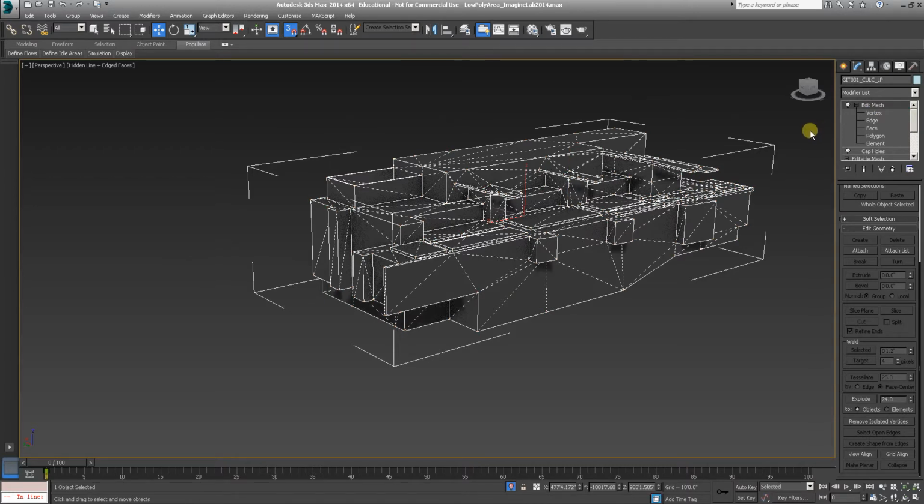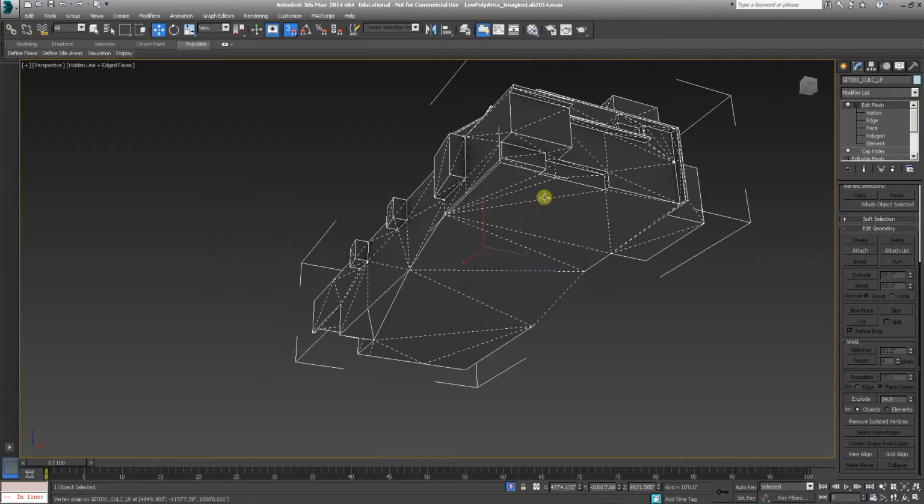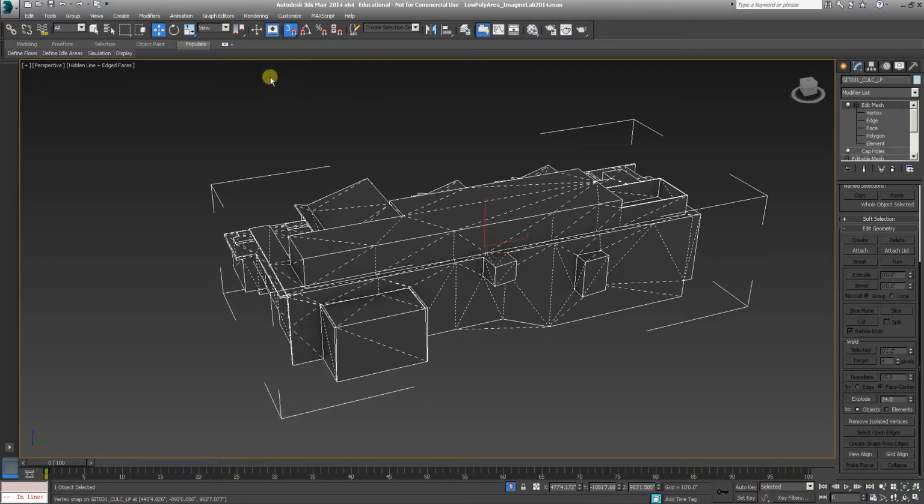If there's any one-off issues, if these get assigned out, you can deal with them. Go ahead and try to cap all of them, see if they pass STL check. And if they don't, and none of the strategies I've shown you here work, you can email me and tell me which building name. You can just copy it out of here in the modify panel, copy that text, paste it, and I'll know which building to take a look at. But just make sure everything's to scale. You don't work at a 64th inch in Rhino or in 3D Studio Max because it's very difficult, and then scale things down afterwards, maybe once you import them in to Rhino and match up with everything else.